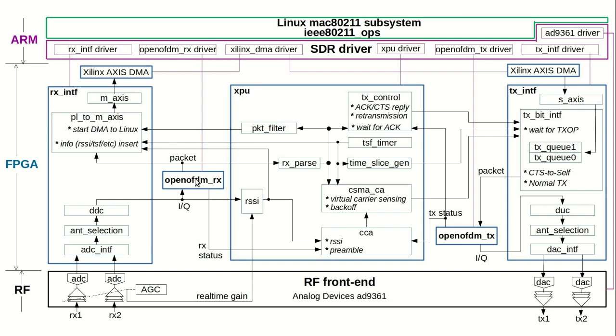Like the openwifi RX, this is the Wi-Fi receiver. All the physical layer processing steps needed are there. You can see the source code. The synchronization, channel estimation, channel equalization, convolutional decoder, CRC checksum, etc. Many details. You can check, you can modify if you have the capability.